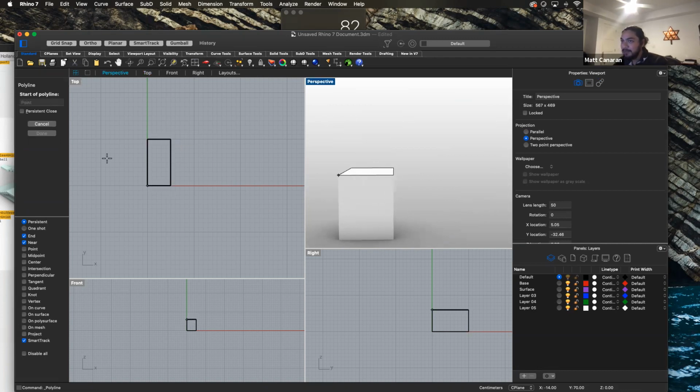And like AutoCAD, when you're mid command, you can type in these little hints, like center or mid or point. I typed in mid, which will help me find the midpoint of this house so that I can draw. I'm going to use the front tool to draw straight up because I want to do the center of the A-frame roof. Let's make that 2 centimeters tall.